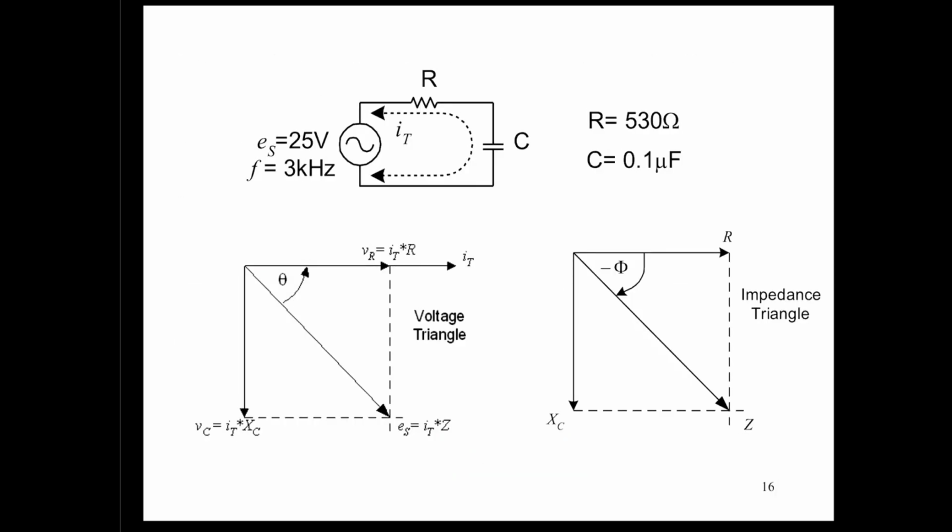So if we look here then, notice how for the impedance triangle of this arrangement, we've got an angle of impedance called phi right here in this triangle that is a lagging impedance. Now remember, when you divide an impedance into an applied voltage is when you get current, right? And so if I divide a lagging impedance into a voltage, I will get a current that is leading. So let's just look at that for a minute.